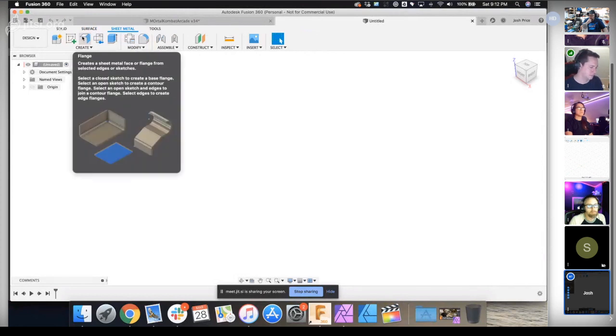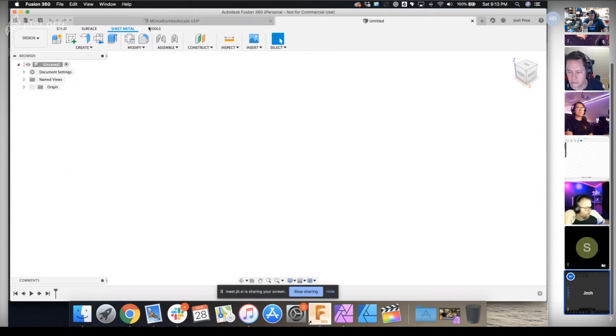You can unfold things and you can give it dimensions, you can give it radius. People do like repeated pattern rolling pins. You can create something on a flat sheet, give it thickness, and then it will wrap itself around like it's a piece of sheet metal. You can unfold things, it's pretty great.